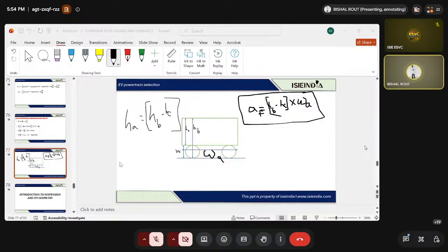So there is a maximum gradability. It is not like the vehicle can travel at 90 degree, right? It will never happen. There is some angle that the vehicle can easily incline. So for that particular angle, what speed is required, what torque is required, that value you can store inside a 2D lookup table basically. Now instead of a complete vehicle model, I'm just stopping it. Instead of using a complete vehicle model, you can use these two things and you can use these two models for the purpose of